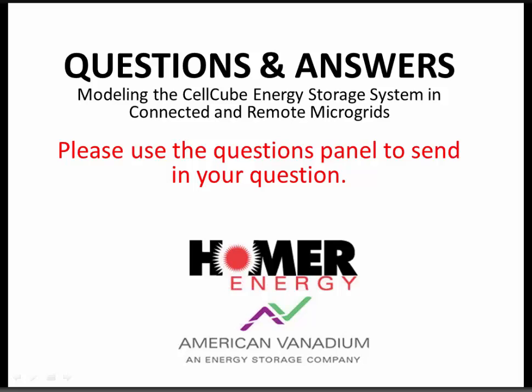Here's another question. For a typical load profile, will the maximum charge and discharge rate support more than one deep cycle per day? Oh yes. As a rule of thumb, there will be about a 1.4 to 1.5 to 1 charge-discharge ratio. In other words, if you charge it for 6 hours, you would get about 4 hours of discharge.